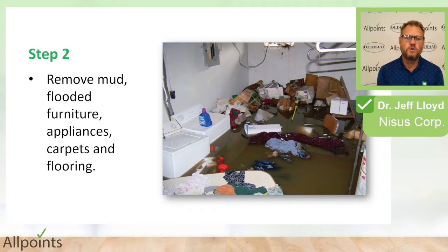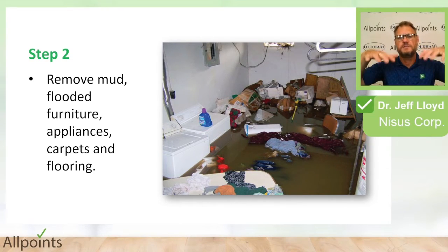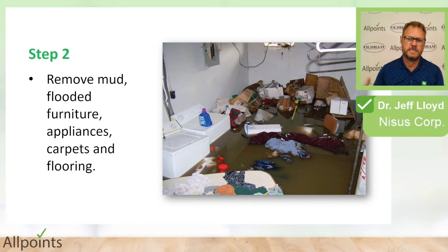Then remove all of the flooded material, all of the physical debris, the mud, clothes, furniture, everything else that could be very haphazardly strewn around the structure as it floated in rooms and then sunk again. So remove all of that. That's going to help you do appropriate treatments. It's going to help you dry the structure as quickly as possible. Anything you want to keep, if you've got a garage, you can put it in. That's great. But a lot of these materials are probably going to be discarded.